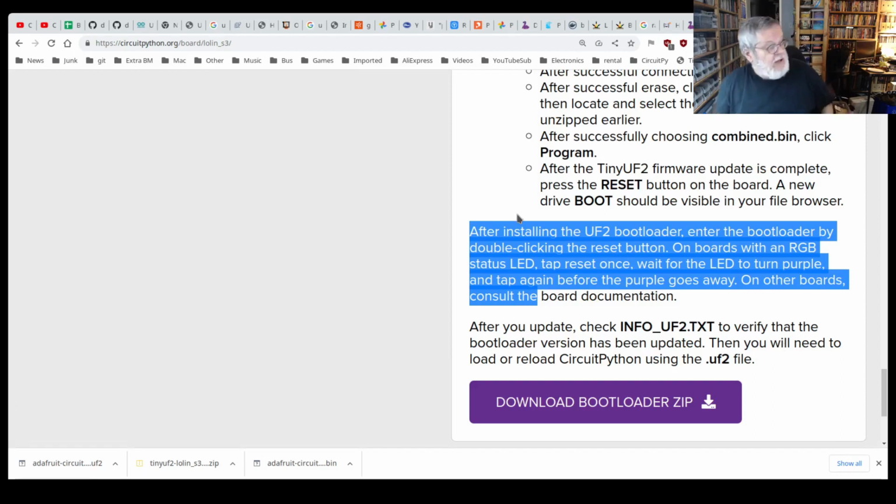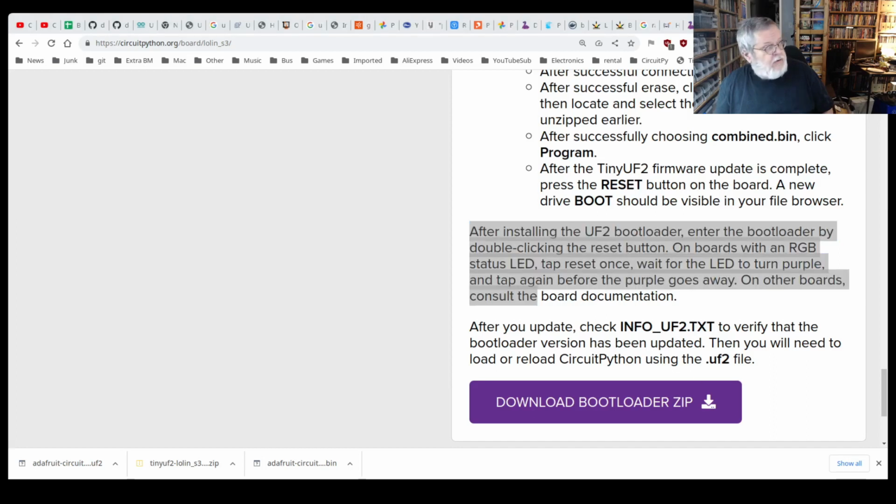I have to make a note of that. It's reset, 0, not that. So where's my notepad? To get to bootloader mode: Reset, then I think it's called 0, then boot 0 button.